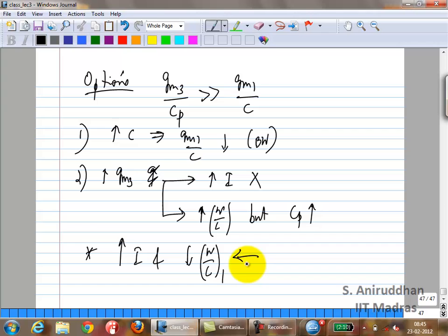So in other words, this has two effects. You are burning more power. That is one fundamental thing you have to realize: you are burning more power because you want to maintain speed. That is directly the speed-power trade-off. What else does this do? As he said, VGS minus VT increases.